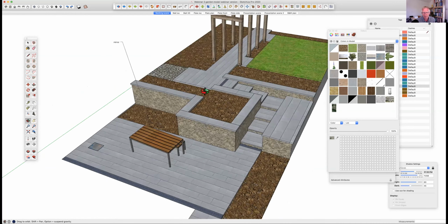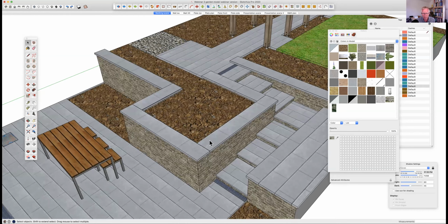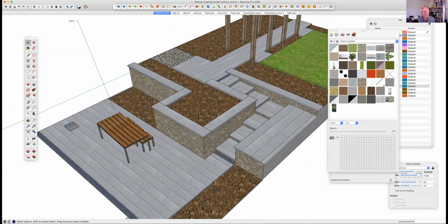Now, if you can't live without it, one of the useful things is you can use a plugin that helps you resize the resolution of that image within SketchUp. So you no longer have to adjust the resolution you're taking on site in camera. I always set things now to high resolution, take very high resolution pictures, bring them in and apply them to my geometry, and then I reduce the file size in SketchUp. The way you do that is download an extension called Material Resizer.